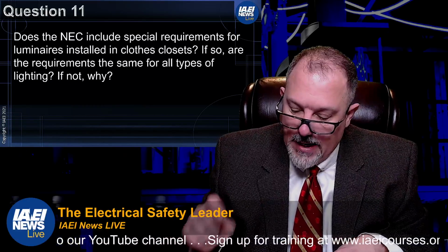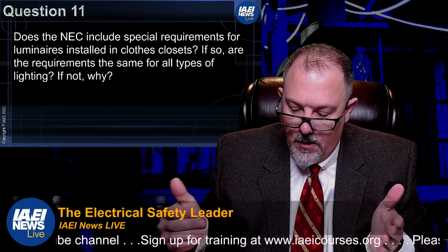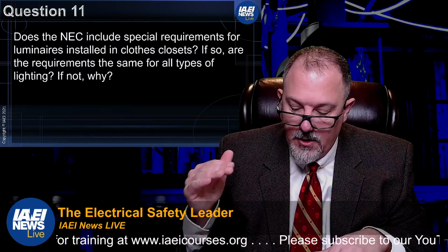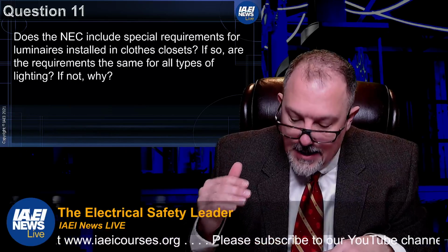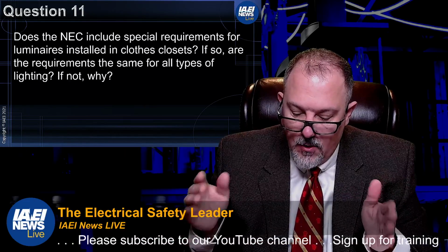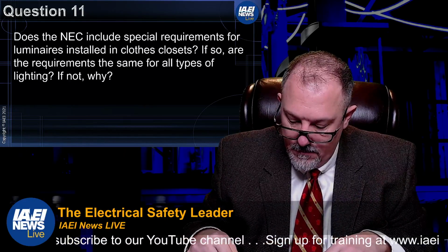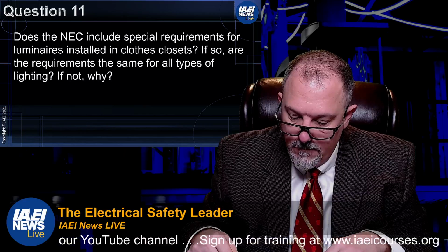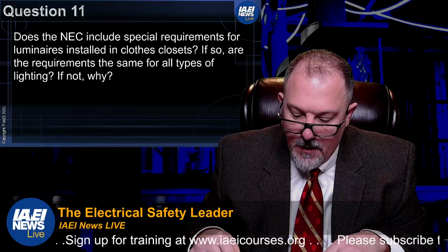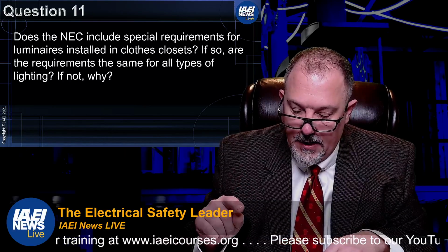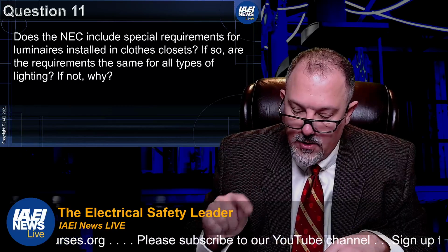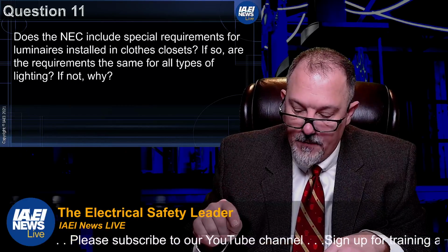The volume bounded by the side and back closet walls and planes extending from the closet floor vertically to a height of 6 foot or to the highest closed hanging rod and parallel to the walls at a horizontal distance of 24 inches from the sides and back of the closed closet walls, respectively, and continuing vertically to the closet ceiling parallel to the walls at a horizontal distance, or the width of the shelf, whichever is greater.